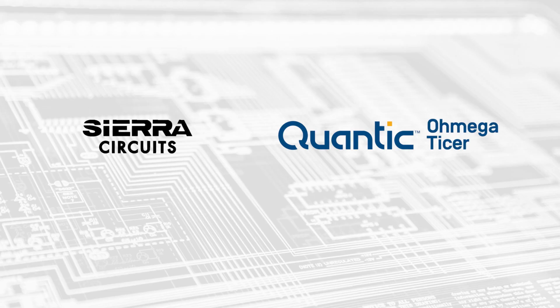And yes, micro vias can be used with this technology. There's no restrictions with that. You can create clearances through it. The only thing that we do recommend, and it's in our design guide, is when you're drilling, let's say you're connecting to a pad on a layer that has resistors, we like the resistors to be offset from the pad a certain amount, so that any heat generated during drilling or any mechanical stresses won't affect the resistive layer, because these are very thin layers. So they're very robust when they're inside the board, but we still want to try to minimize any heat or stress that might affect it during that time.